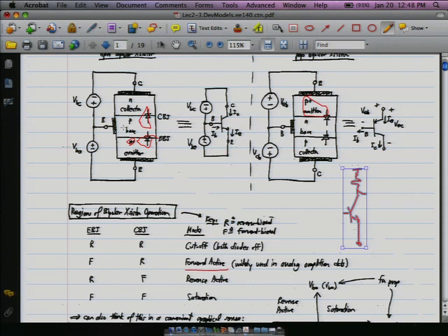So you can sort of flip MOSFETs, but with a BJT, you really can't because your gain just becomes horrible. And so while there are occasionally uses for cutoff or devices that are close to cutoff or saturation, and there's certainly uses for forward active, I haven't really seen anyone try to use reverse active. It's just not common, just not useful.